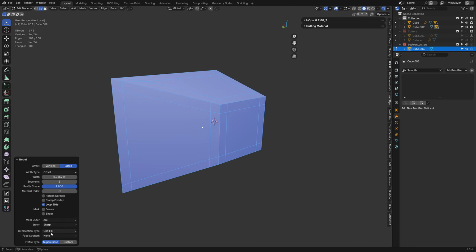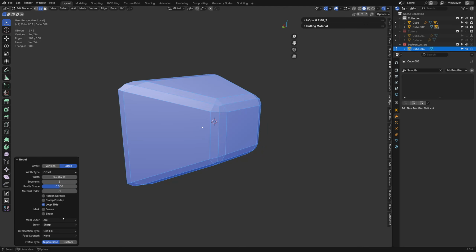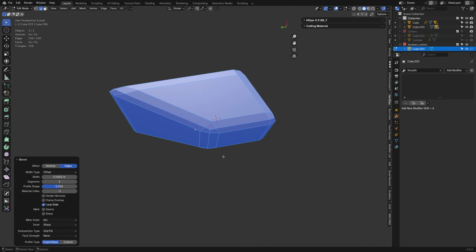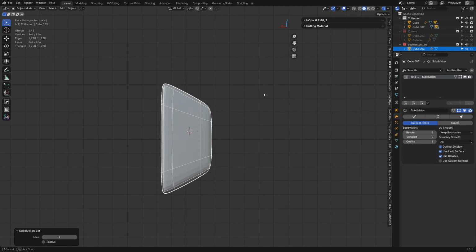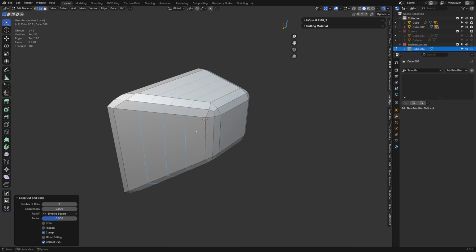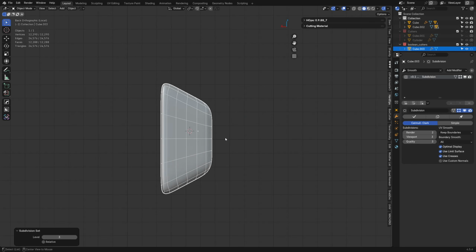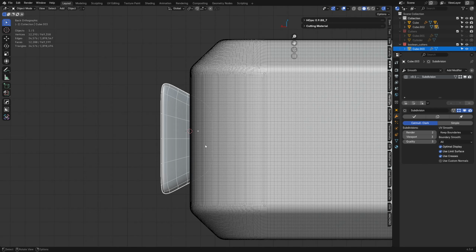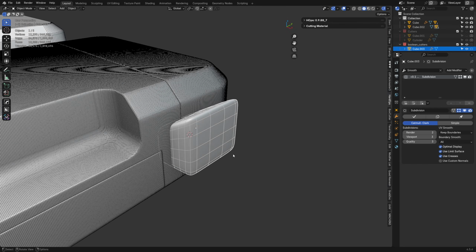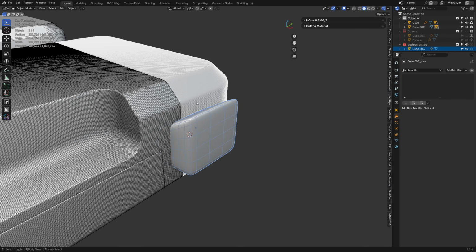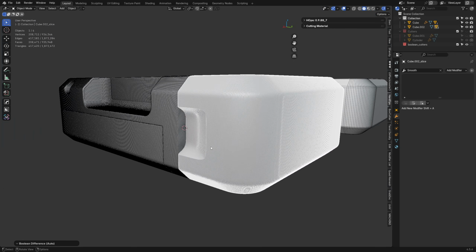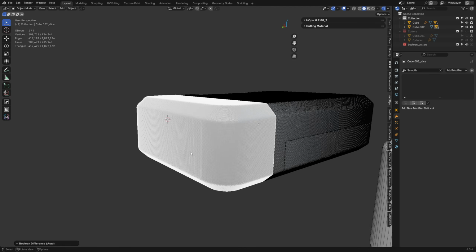And you can see I did something goofy there. I don't know what I did. I'm going to reset that real quick. All right. If we bevel it like this whole area is rounded. Okay. Careful with that. If you don't want it rounded, add some loop cuts. Okay. But now it won't round as much, all right, in the middle of those faces. So it'll be a little bit more flat. And when we do the Boolean subtraction, we get that. Simple enough. We wanted it on this side.